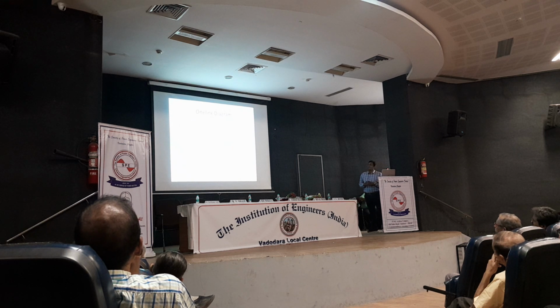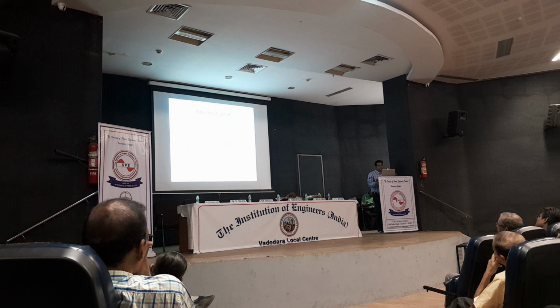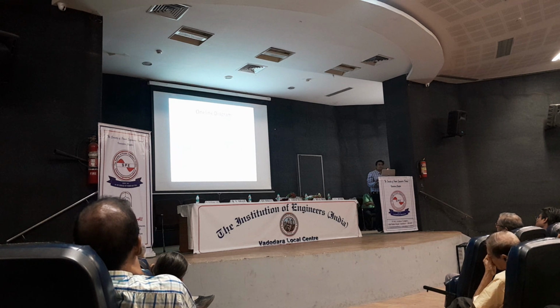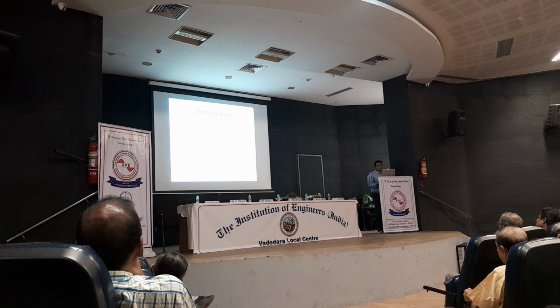When you open a new file, it will look like this. In Draw you can see that the network option is there. So from the network option, whatever we have discussed so far, we first select the bus, then enter the bus details and bus voltage ratings. After that, we enter the generator details and attach the generator to the bus. As you know, we have selected that the generator is connected to the slack bus. So if you pay attention, you will find that this generator is mapped to the slack bus.